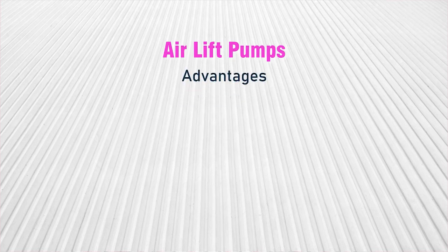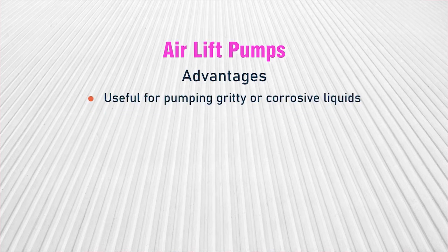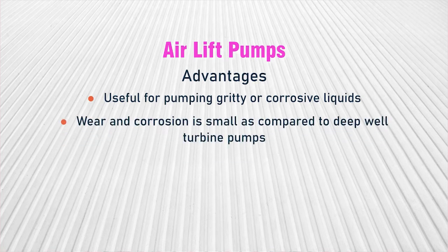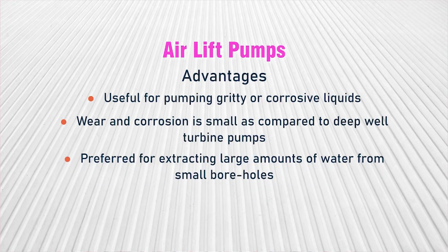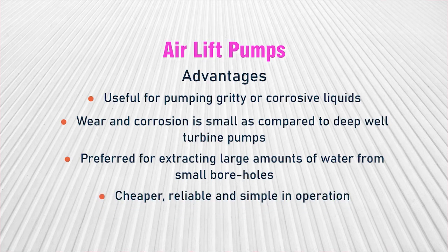There are a number of key advantages offered by airlift pumps. One of the first one is that airlift pumps are very useful for pumping waters that are either corrosive or gritty. The wear and corrosion in case of airlift pumps is small as compared to deep well turbine pumps. Airlift pumps are generally preferred for extracting large amounts of water from small boreholes. These are cheaper, reliable, and very simple in operation.